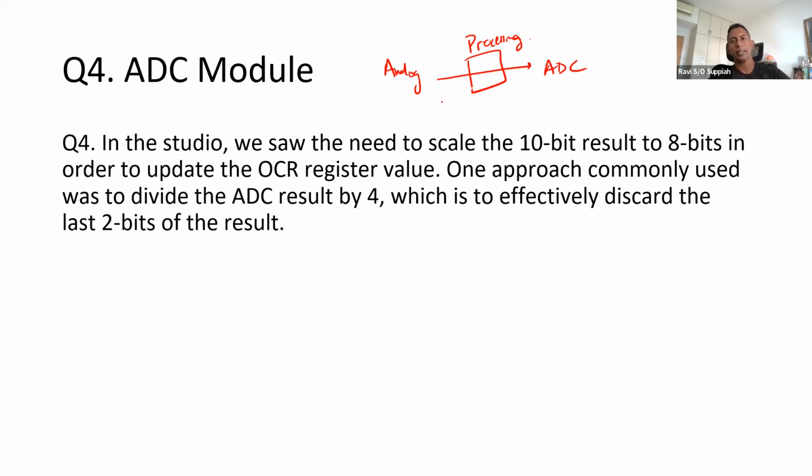Again, this is very important when your signal is very small, maybe 0 to 1 volt, or 0.5 volt, but your ADC is from 0 to 5 volt. So you want to extend the range of it using an operational amplifier and providing the necessary gain and things like that.